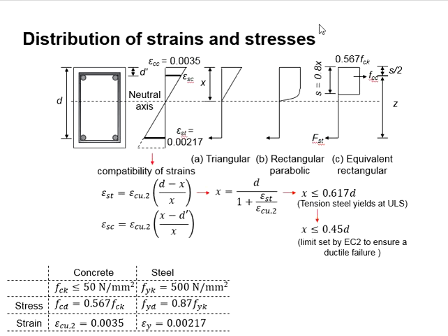At the same time, the neutral axis relocates, becoming further away from the top beam until it reaches a state where the member enters the over reinforced condition. We will need to prevent this. In order to prevent the member from being in the over reinforced state, we will have to set the maximum limit of the x here. How do we do that?